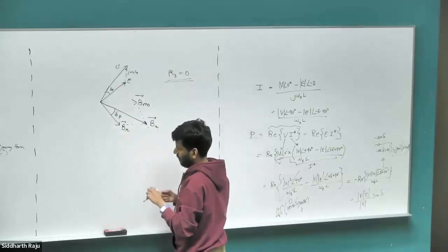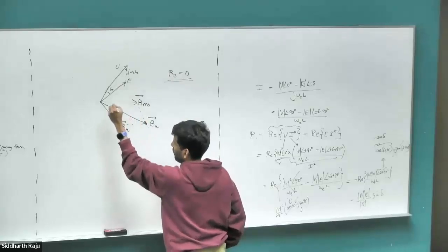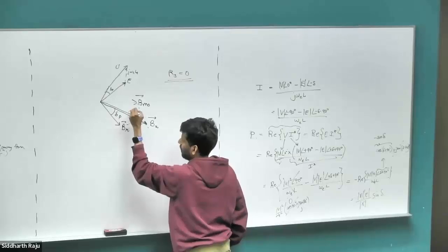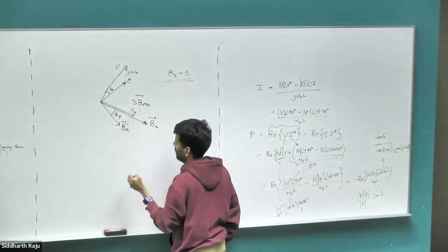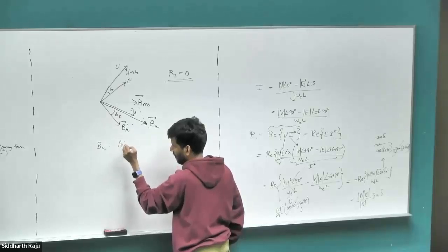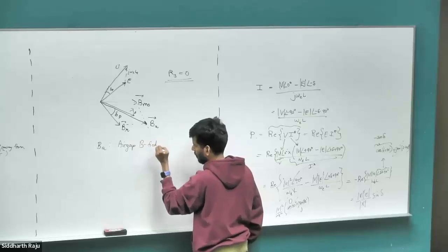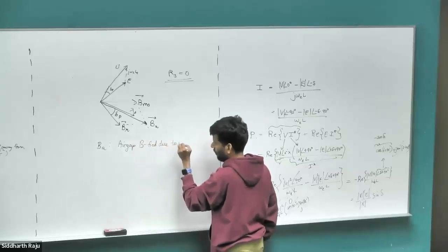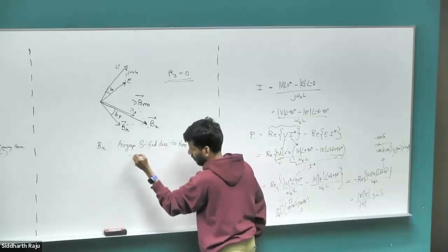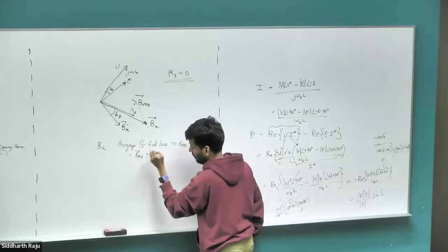So let's look at what the reason for this is. Along this direction would be the vector for, we haven't introduced this term, but it would be used in any vector control textbook, the term lambda S. BA is the air gap B field due to BMS and BR, so this is equal to BMS plus BR, vector summation.